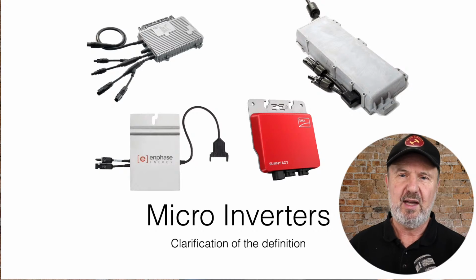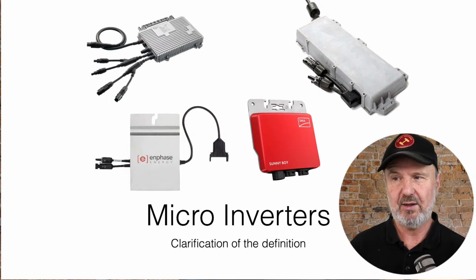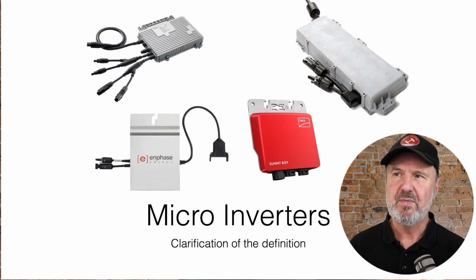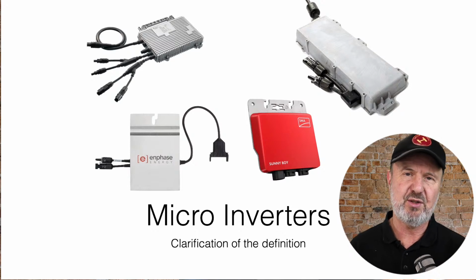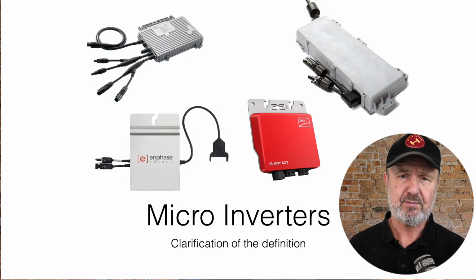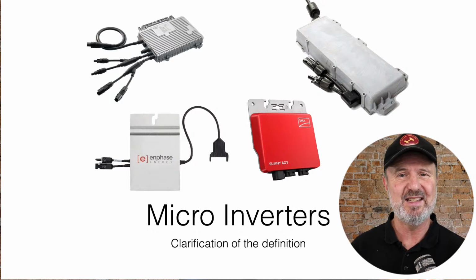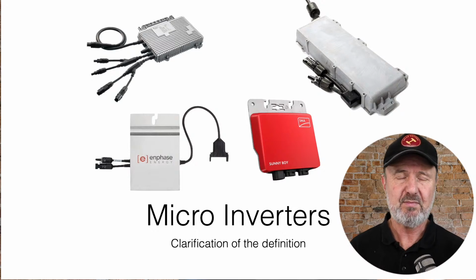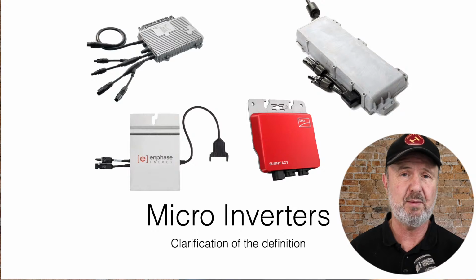Microinverters. Now, generically, optimizers, DCUs, and microinverters are all known as module level power electronics, or MLPE. I won't use that acronym much, but I'll just talk about microinverters and optimizers. Microinverters have a similar function to an optimizer, but they convert from DC to AC. So you've actually got an AC network up on your roof, and the highest DC voltage is one panel, because there's no strings of panels connected together in series or DC strings.